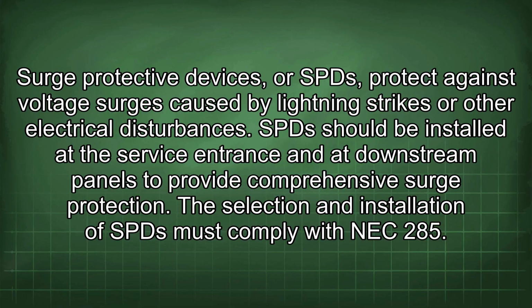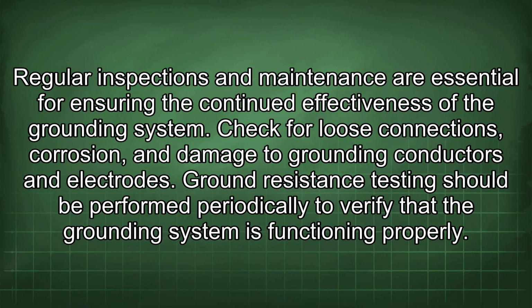The selection and installation of SPDs must comply with NEC 285. Regular inspections and maintenance are essential for ensuring the continued effectiveness of the grounding system. Check for loose connections, corrosion, and damage to grounding conductors and electrodes. Ground resistance testing should be performed periodically to verify that the grounding system is functioning properly.